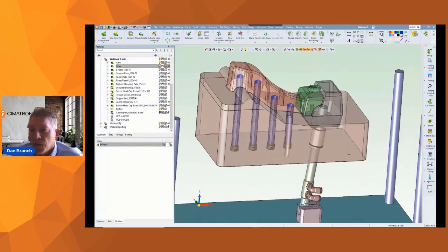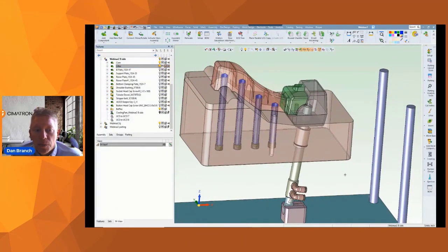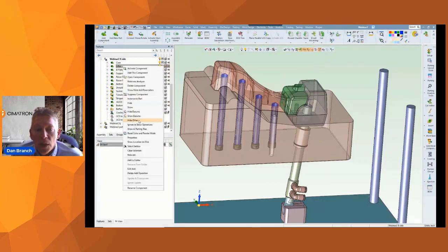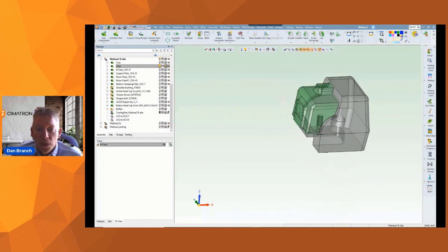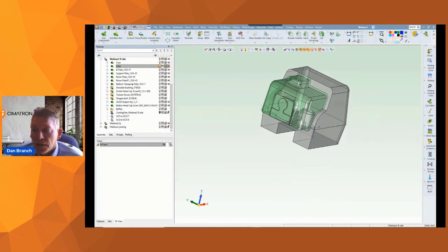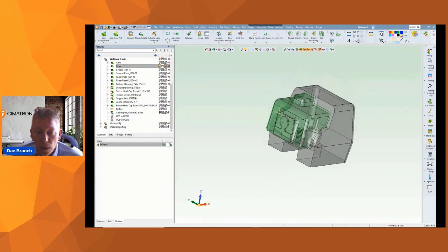And I could design a few conventional cooling lines into the lifter, but it does have a lot of molding surface, and that limits the areas I can drill into. So the ideal way to get the best cooling throughout this lifter is going to really be with conformal cooling. And I know a lot has been written about conformal cooling in the last few years. I think the benefits are really getting well known.